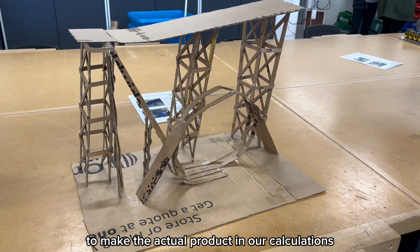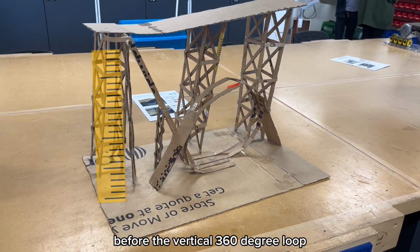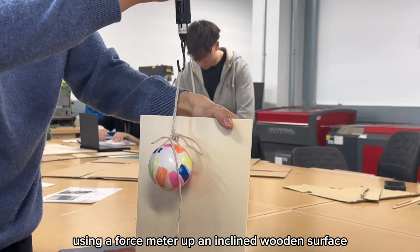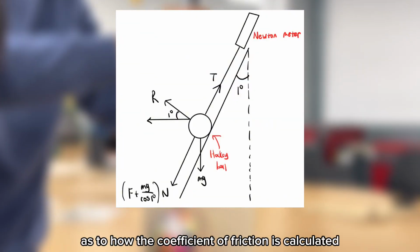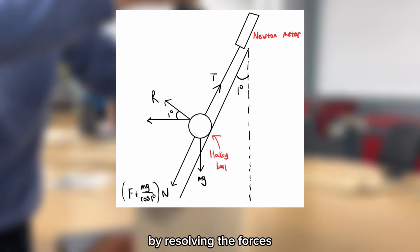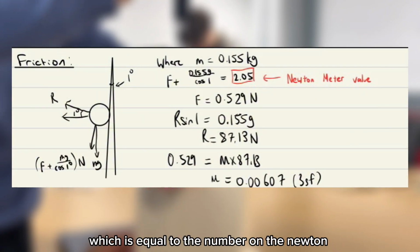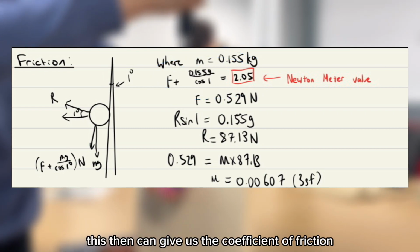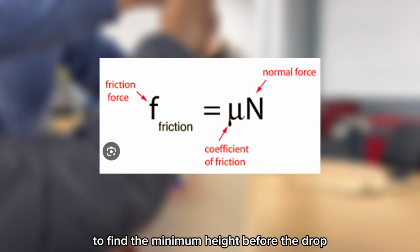In our calculations, the main focus was calculating the minimum height of the drop before the vertical 360-degree loop. We considered friction in our calculations by dragging the ball using a force meter up an inclined wooden surface. This free body diagram will give a clear explanation as to how the coefficient of friction is calculated. By resolving the forces, we can calculate the resultant force R, and the tension, which is equal to the number on the Newton meter, is also equal to weight plus friction. This then can give us the coefficient of friction, as we already know the R value and the F value, which will be used to find the minimum height before the drop.